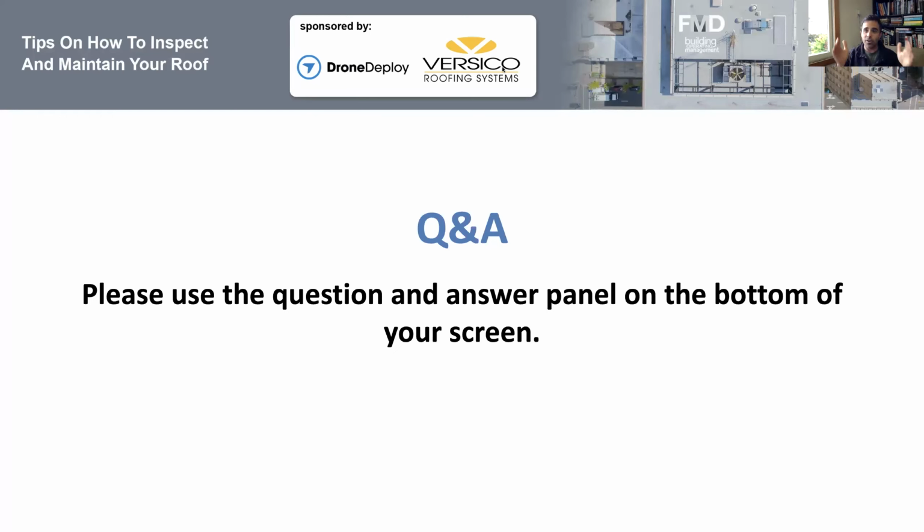Time of day, very important. You have to fly half hour after sunset. That's very standard for thermal roof imaging. Chris, anything to add? That's the type of things we recommend.